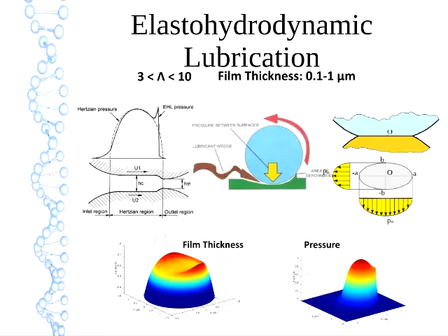The size of those two differences will change depending on the conditions of the contact. And when you look inside the contact, you've got generally flat parallel surfaces, and then at the end it dips down. That's correlated to the same spot where you've got the pressure spike, and that happens in order that the continuity equation, conservation of mass, is maintained.